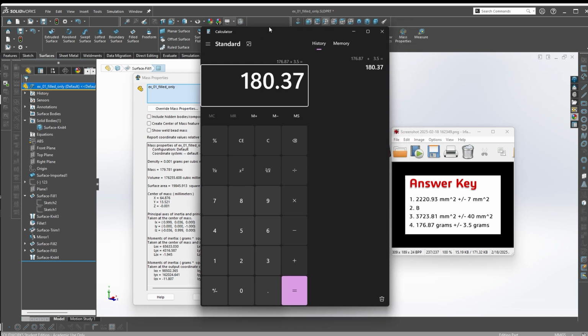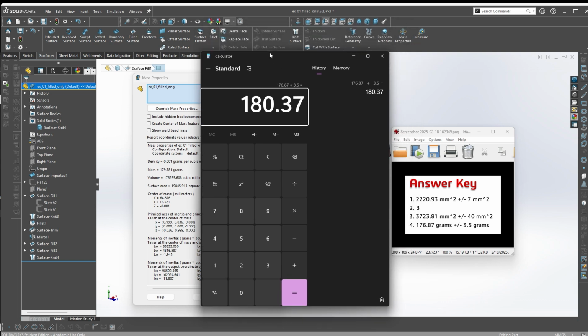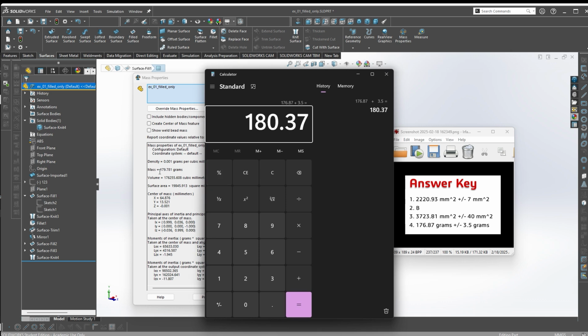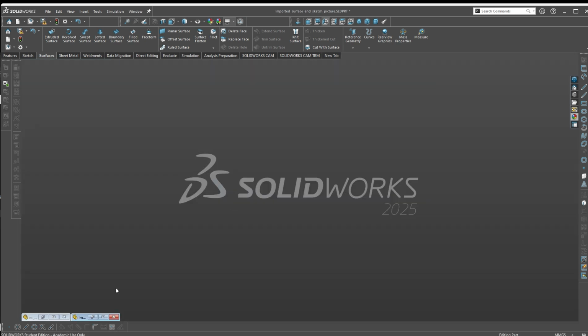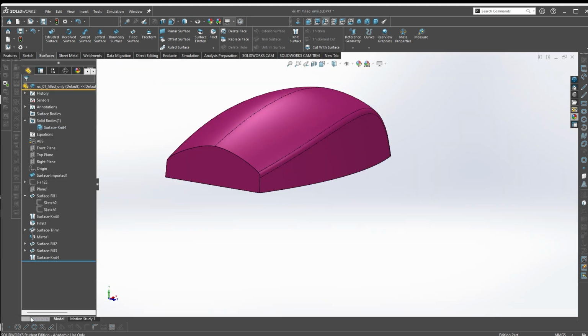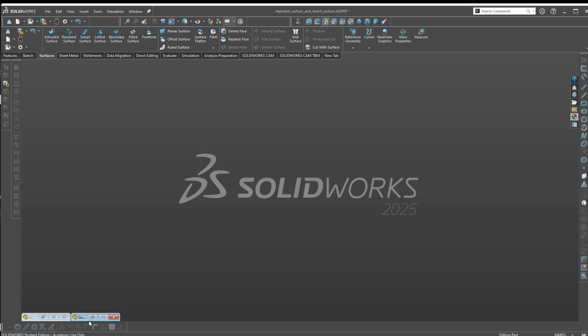So you can see in this case, using that different approach to that first surface did create a little bit of a discrepancy. In other words, using the filled surface for that first edge versus a swept surface gave us a slight deviation from the original. Okay, so just something to bear in mind with the filled.